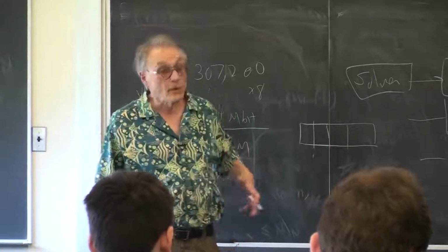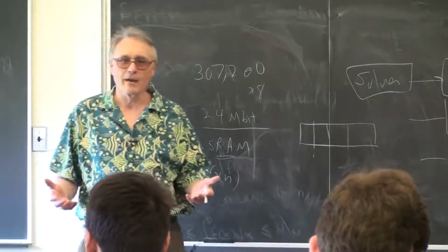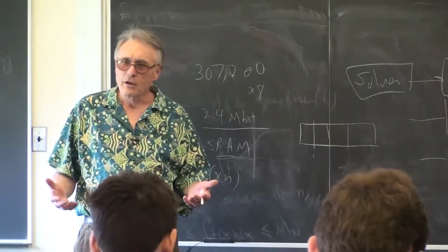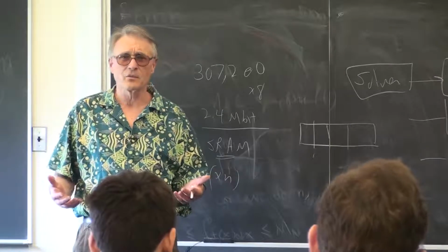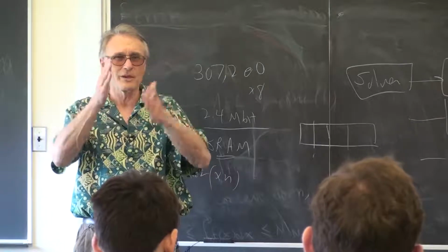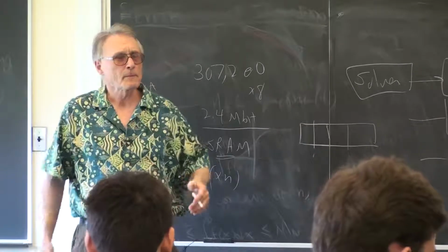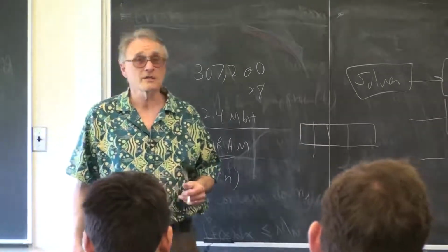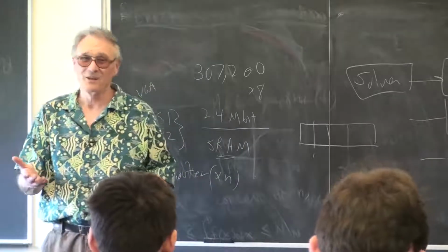So it worked, except that it was only writing every other pixel. So what the hell is going on? I was getting this weird screen door effect of one image transparent through the other because only every other pixel was being written. And it turns out it was because I was only writing the lower byte.